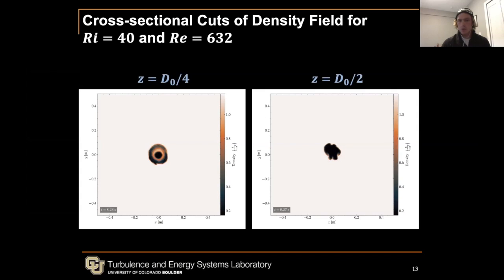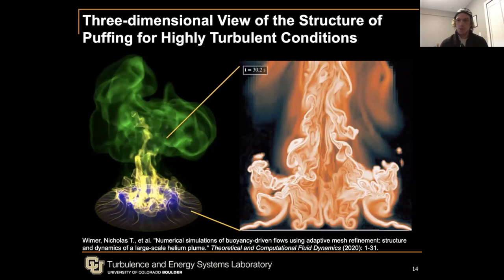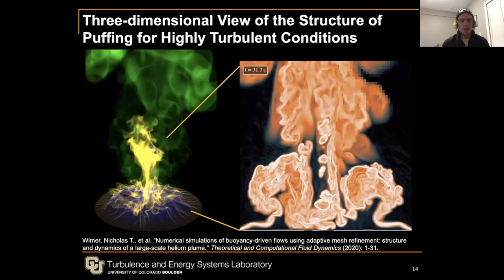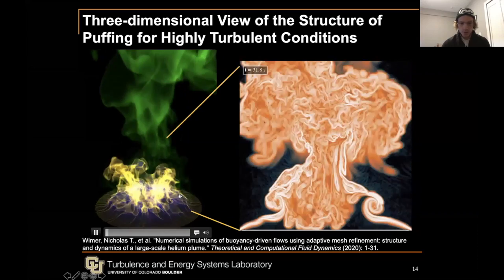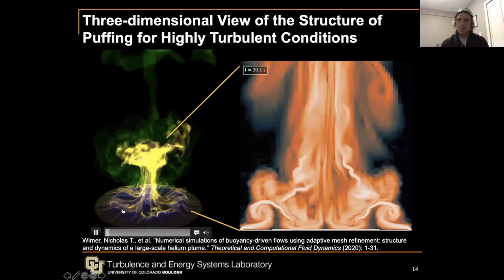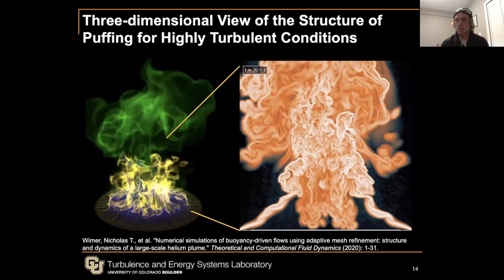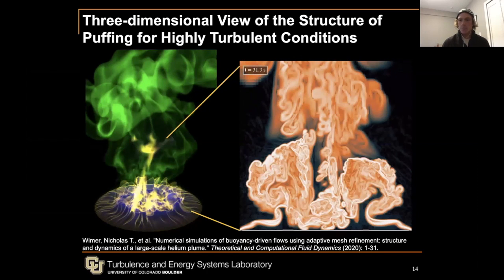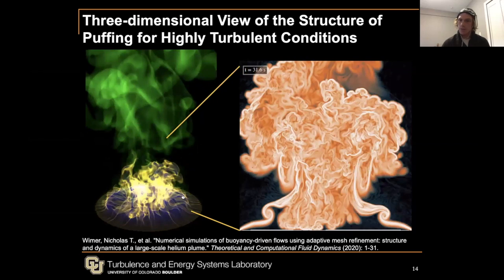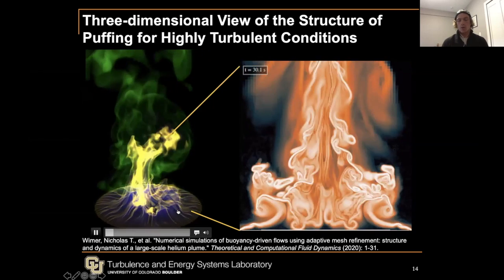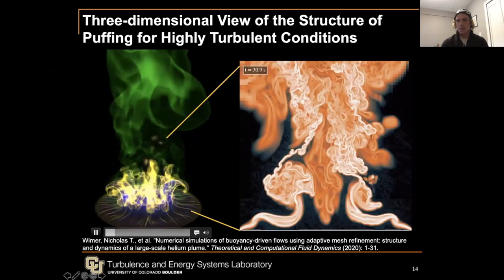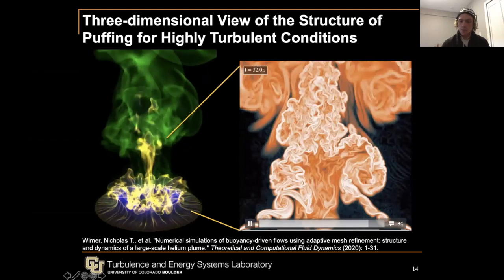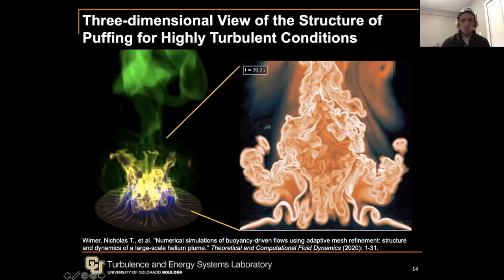And this is really important. This was a visualization that my lab mate did a few years ago with yt. These structures you can see in 3 dimensions much more clearly. These are essential, as the community puts it, to accurately modeling buoyancy-driven flow. If you don't resolve these finger-like structures in a very turbulent condition, then you don't predict the correct statistics in the flow. And on the right here, I'm just showing a density gradient magnitude. So these are very important.